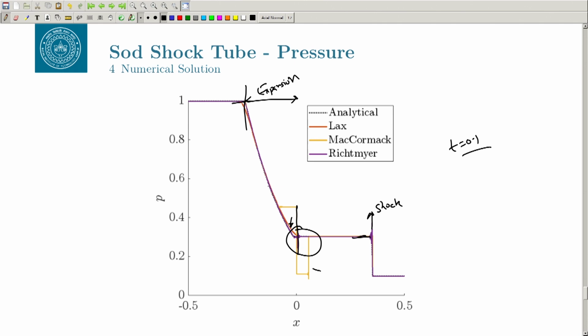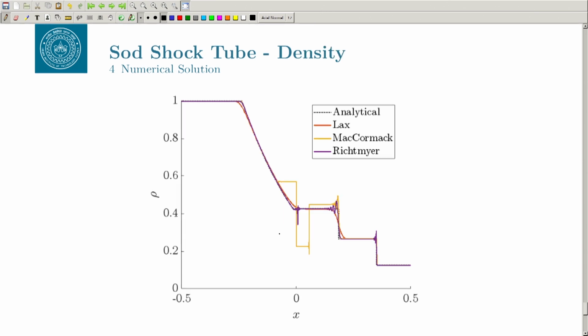Here is the pressure decay because of the expansion, and you cannot see the slip line or the contact discontinuity here, but if you go to the analytical solution for density or even all those solutions, this is my expansion, this is my shock, and this is my contact discontinuity or contact surface, and this entire thing is the expansion fan, because it is a continuous phenomenon. This is an isentropic expansion, entropy is not getting lost, but the shock is non-isentropic. It is adiabatic, but not isentropic.